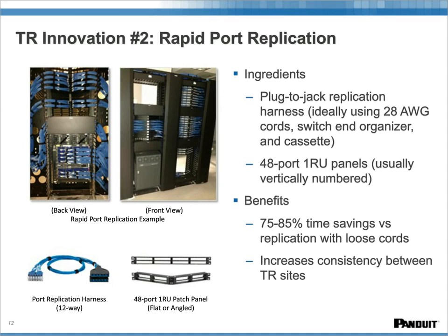versus loose cords? Well, typically there is the running of the equipment cord from one side of the rack to the other. So typically there's a little more dressing required, and therefore the time savings is greater when the cords are bundled together. This also can increase the consistency between telecom room sites and make it very easy for installers to achieve a consistent implementation.